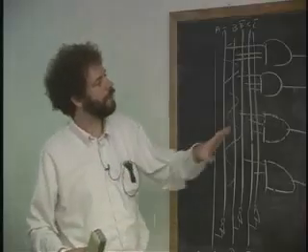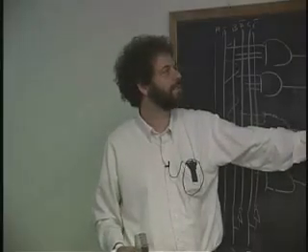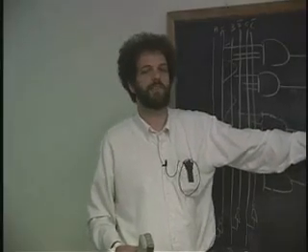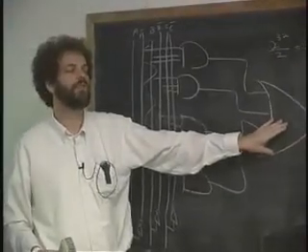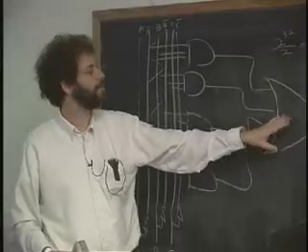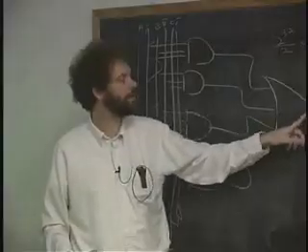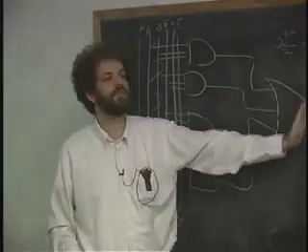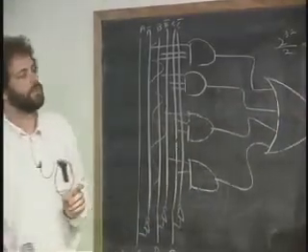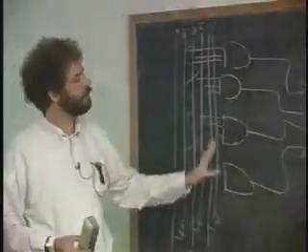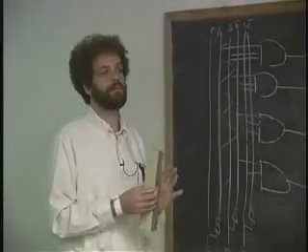Even worse than that, we have 2 to the 31 wires going into this big OR gate. So it's an OR gate with 2 to the 31 inputs. I've never seen an OR gate like that, but if there was one, it would be incredibly slow. Again, because it would have to consider all of these things, and in determining what the output should be, there would be a lot of charge that would have to get transferred to figure out whether one or more of these is in fact high. Okay, so sum of products sounds like magic, and it is for some functions, but not for all.